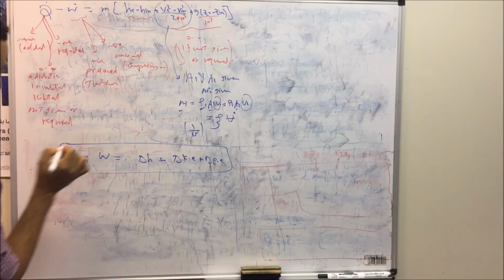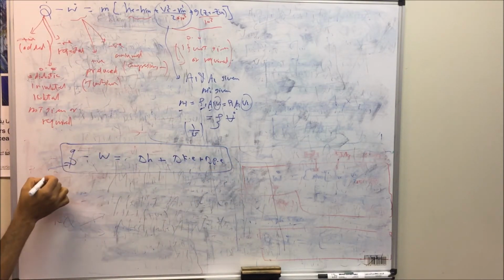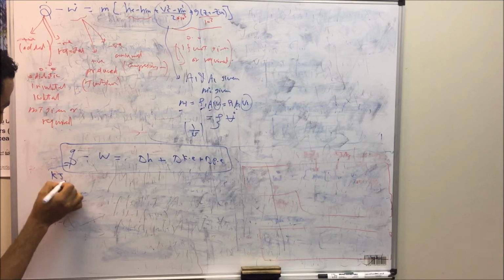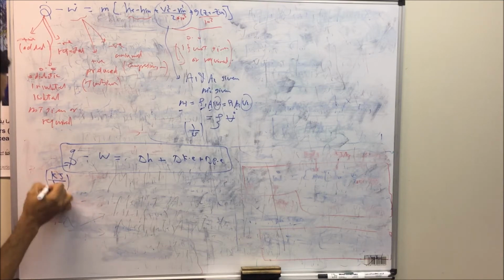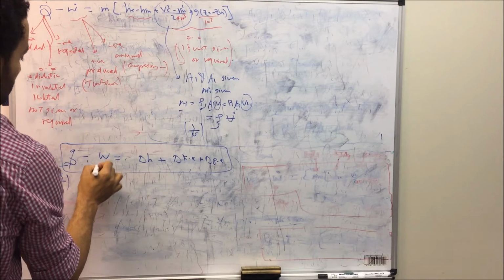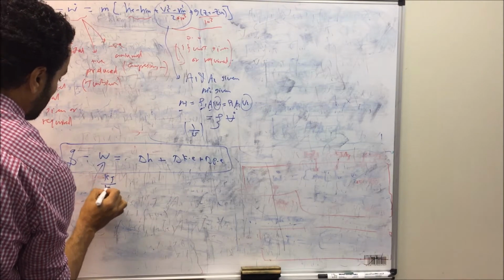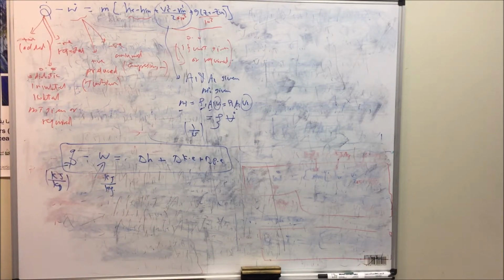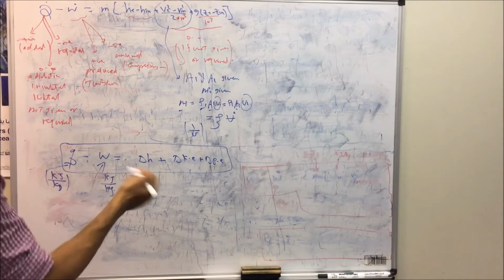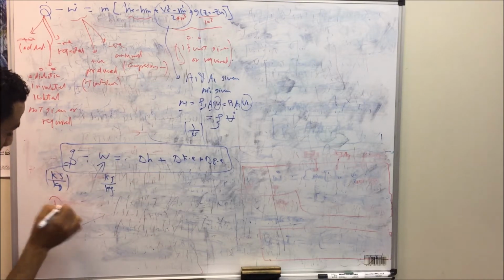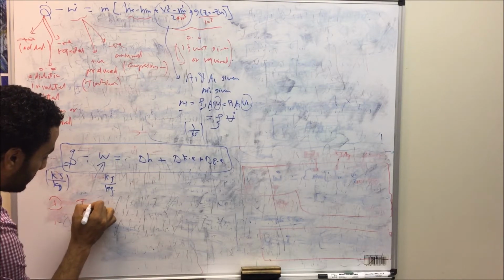And in this case, the heat transfer and work are calculated in kilojoule per kilogram. All of these terms should be in kilojoule per kilogram. Okay, so this is the reduced equation per unit mass flow rate. Let's start actually with some steady flow devices, starting with turbine